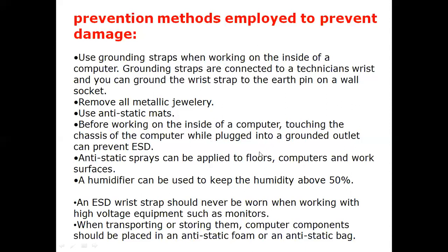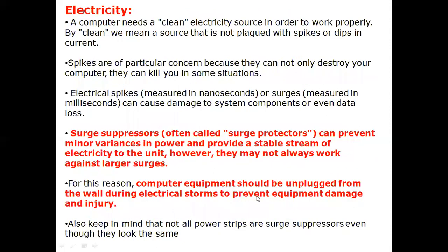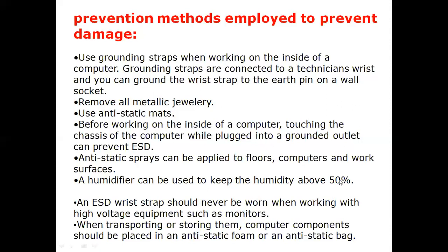Anti-static sprays can be applied to floors, computers, and work surfaces. Where you are working, you should use anti-static sprays to avoid problems due to electrostatic discharge. A humidifier can be used to keep the humidity above 50%. I told you that humidity should not be very low, and it should not be very high. So 50% humidity or above is okay.